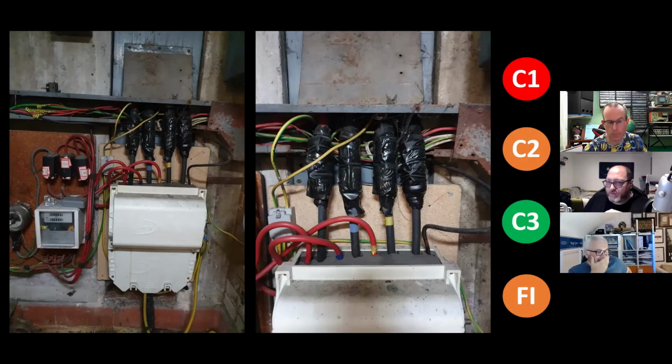What do we think it is supply-wise? Because normally on these sorts of things, you do see earths coming in from the joints, but I'm naturally assuming that cable there is coming up underneath, going into the joint, but then again, you've got earth conductors going round. So there you go. You can see that conductor there goes around the bottom and up into that insulated earth terminal there, probably to facilitate these. You've then got this as a separate conductor coming in and coming off. That one bends and goes up with the header, doesn't it? The bigger one.